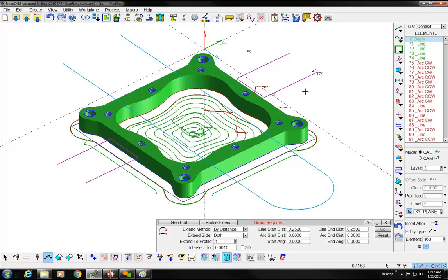Okay, I just got a message that I was disconnected, so I don't know if I still am. But if you had a lot of roughing passes that you wanted to see, you could stop the show path right after the roughing, hit the F8, and then start it back up again, and you're just going to see the finish passes.